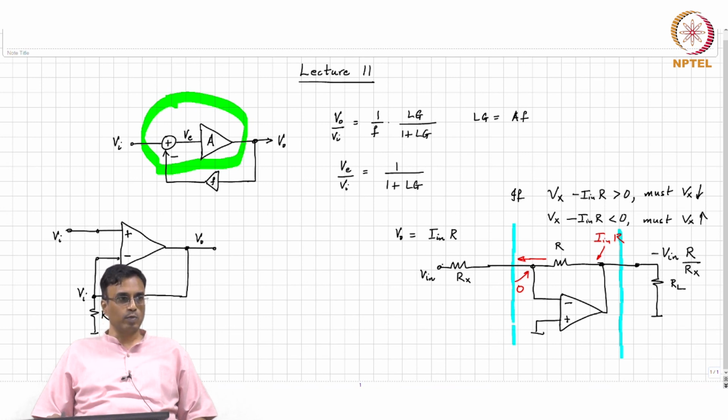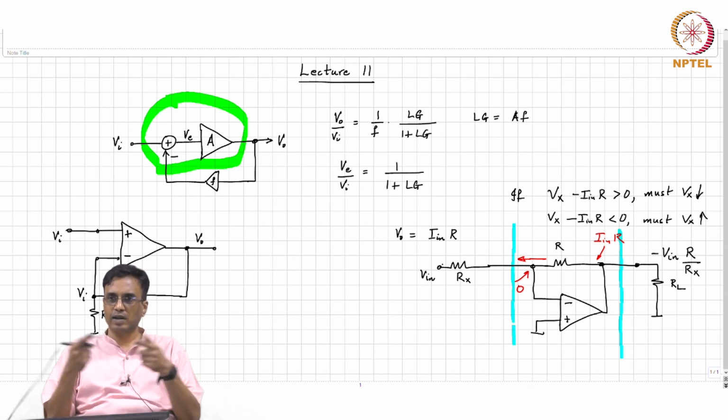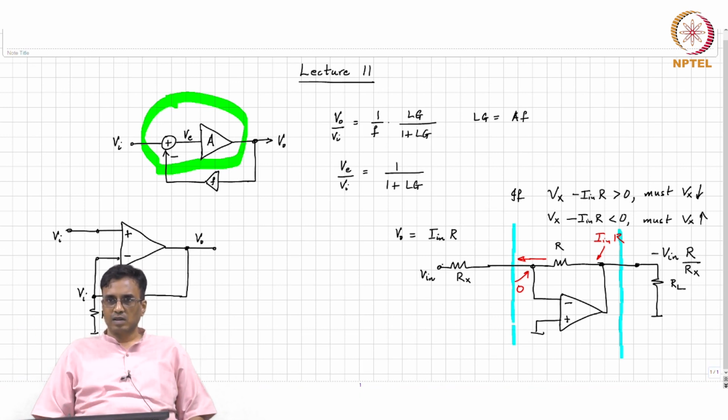Yeah. So basically, if you take V1 and V2 and connect them together through two resistors, the midpoint will give you the sum of the two multiplied by some fraction. Since we are only comparing it with 0, that fraction does not matter, correct.